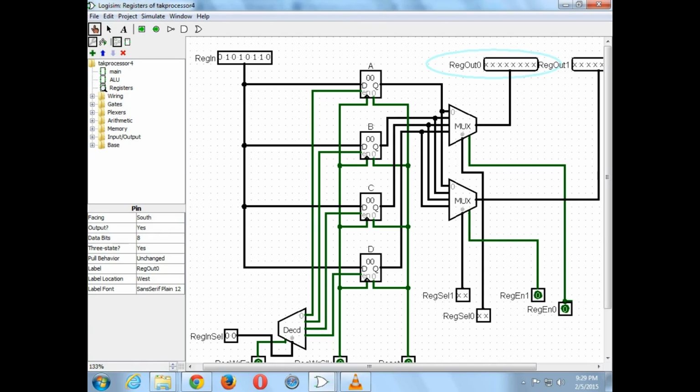So after that, yes, once this register is updated, it will go through the mux and change the register output. The register output will in return change the input into the ALU, and then the ALU will change its own output, which means these bits in return will also get changed. But nobody is going to update because the 0 to 1 transition is already over. And we have to specify on the decoder if we want it to change. So that's why